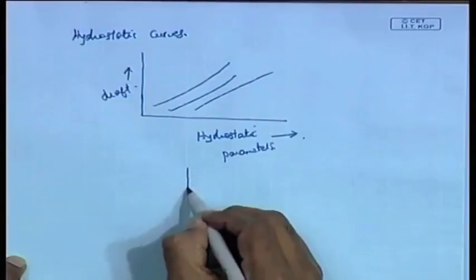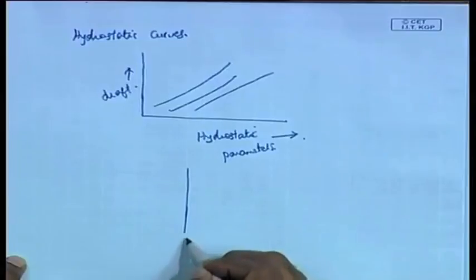I have already explained to you what is known as the sectional area. If you have a ship like this, and if you slice the ship like this, these areas are known as the sectional areas. This area, that is the part of the area that is under the water and through which you have produced the slice, is known as the sectional area. So, you can draw the sectional area at various drafts, that is also a hydrostatic curve.